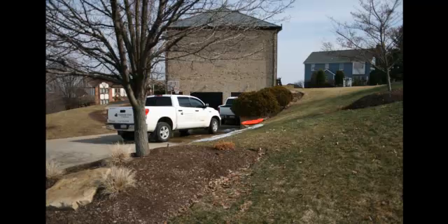While taking these pictures, we are also shooting elevation points as we walk through the property with a laser transit. Areas like this are mandatory to shoot exact elevations, which will enable our designers to know exactly how many steps are needed, how far back the steps will go, how far the wall can go back into the hillside to provide more driveway space, and how high the wall will be. This essential data is what enables us to portray an accurate rendering that virtually eliminates add-on costs and unforeseen labor discovered during construction.